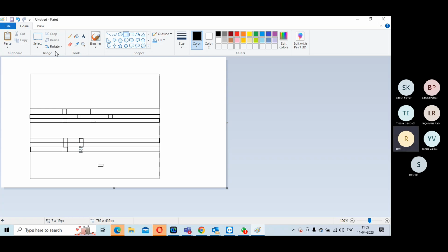Similarly, you can add ECO-able filler cells, like 50% can be ECO-able filler cells, 1 of every 2 filler cells. Because ECO again has a lot of problems. It will add connectivity, and then all your metal layers will start troubling you.